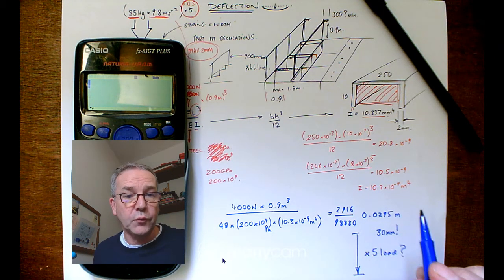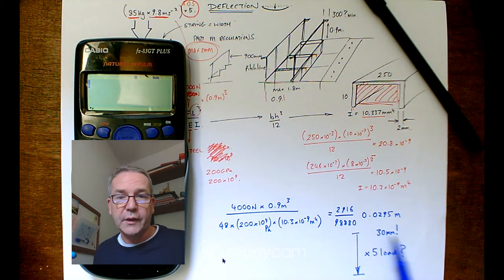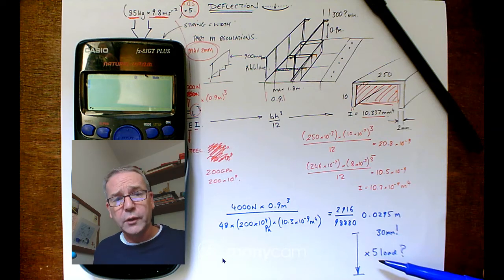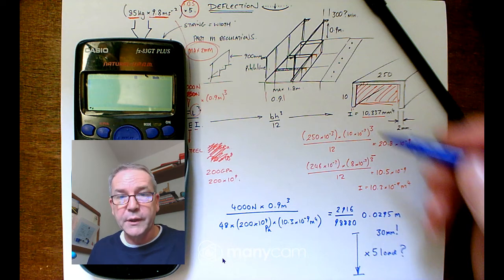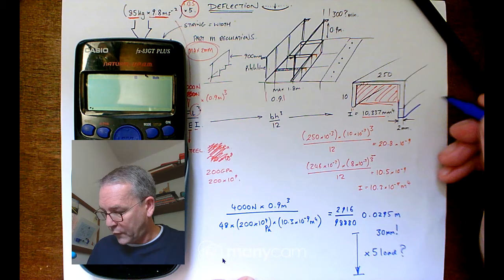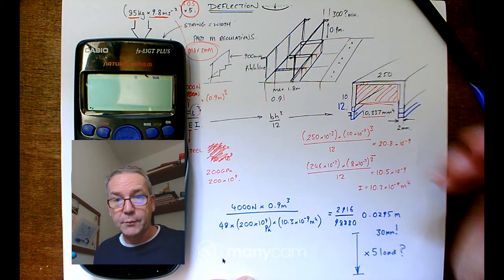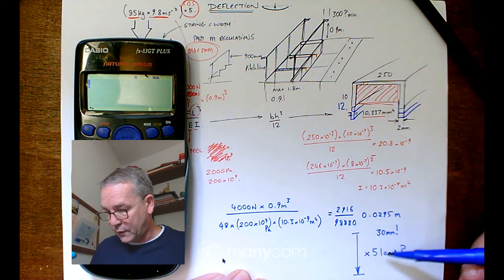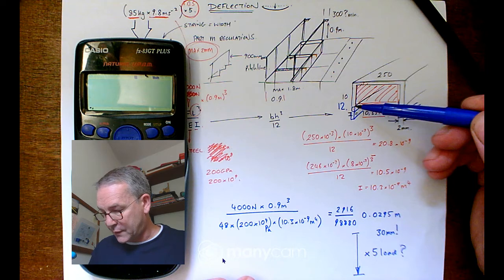This now means we need to do some research. The calculations work out, but that's too major a deflection for me to live with. I've got two options. I can stick with the multiplication of times 5 on the load, which I think is really too much, or I can look at, do you remember we talked before about changing this, adding a couple more millimeters here? If we added 2 more millimeters there and there, we change that to 12, that might also be a solution. So we might be able to stick with this times 5 load and use the inertia with 12 millimeters on the end here and see what that did to these calculations.